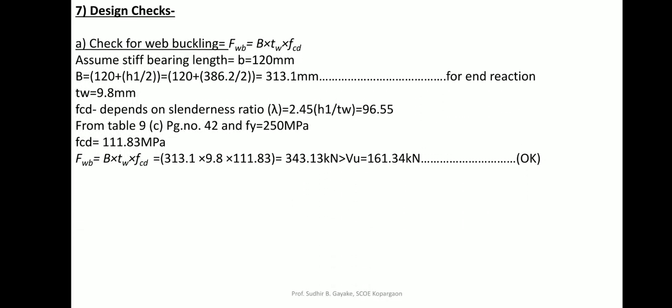Initially, web buckling check. Now, for web buckling check, your FCD value is to be considered, and FCD depends upon KL by R value.